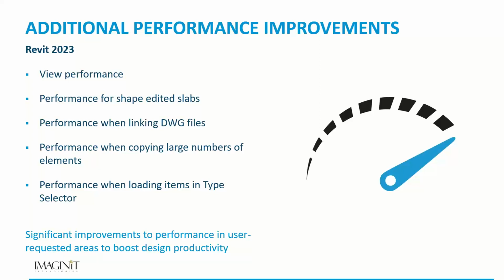Users who've tried to use this have reported that Revit views, depending on the large number of MEP elements, needed to be optimized. In other words, it was working kind of slow. So in 23, we're seeing about a 25% improvement in opening and navigating views containing large numbers of MEP.